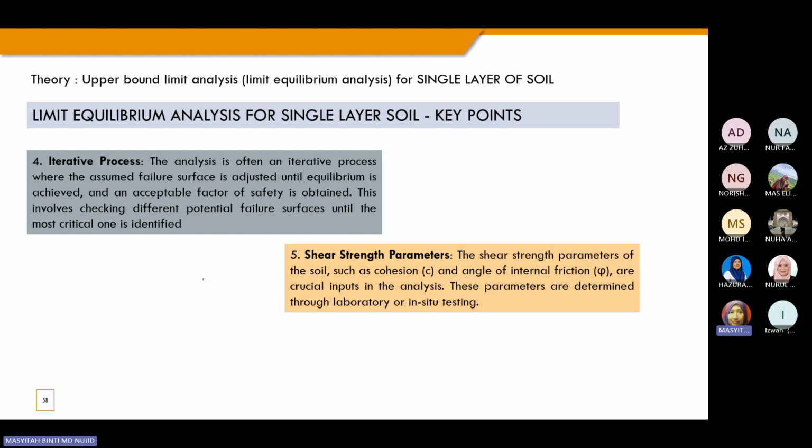The theoretical part is whether you analyse as a single layer or as a double layer, two-layer strata. If two-layer strata, how do you consider the failure mechanism: the conservative one, or the very good one as a slope failure mechanism. If you have done two calculations, you need to justify which is better, based on the input data from the soil parameters.